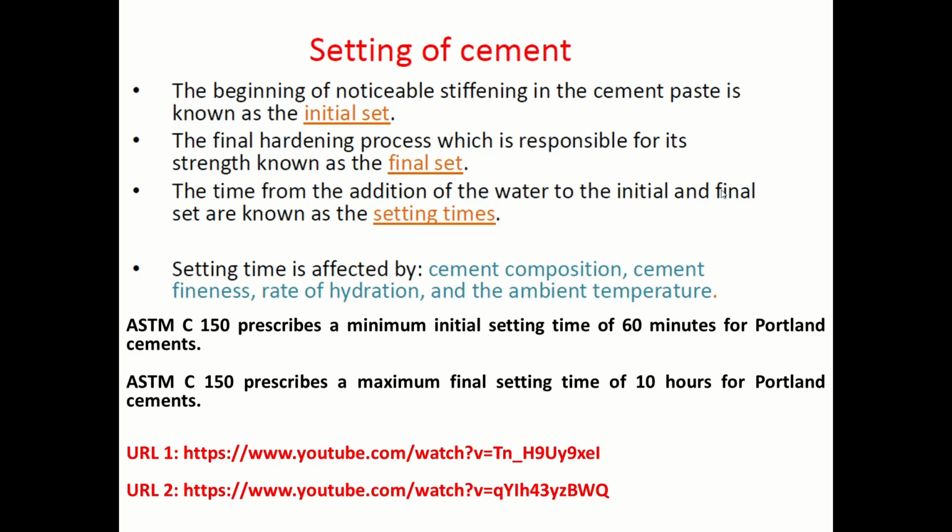But for the initial and final setting times, there is one important terminology that we have to know, which is called the consistency of the cement, which is the amount of water divided by the amount of cement multiplied by 100. It will be in percentage. So we can see through this video.